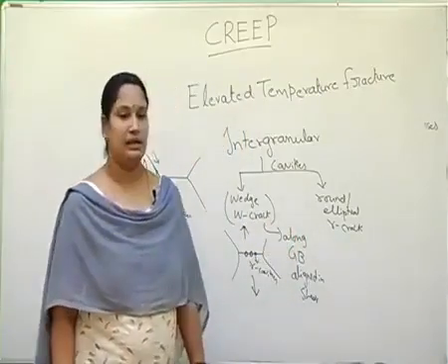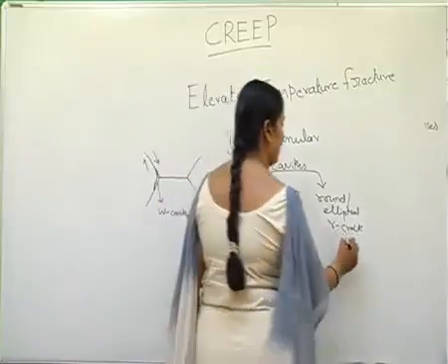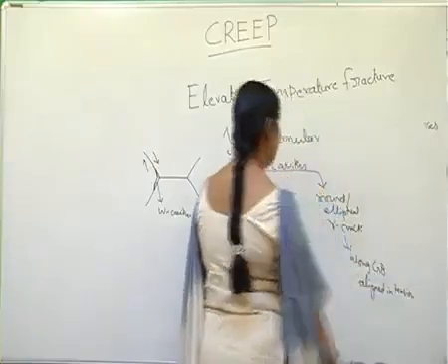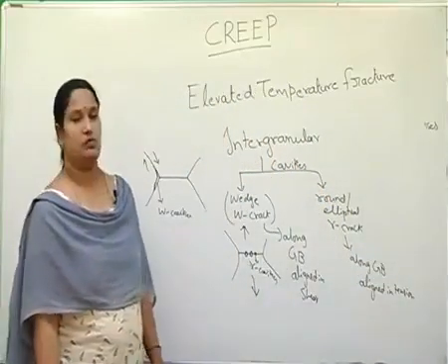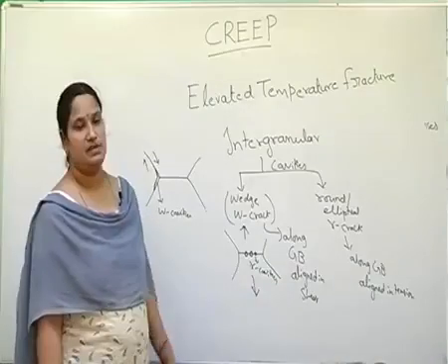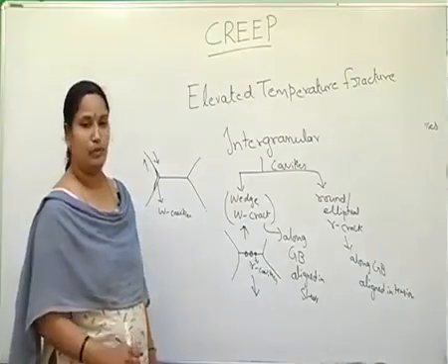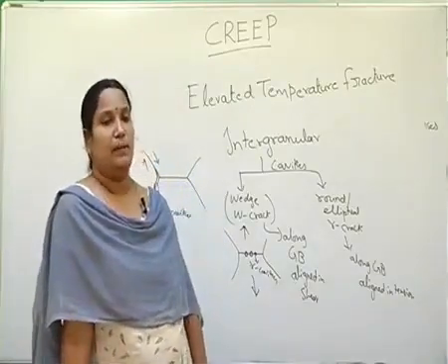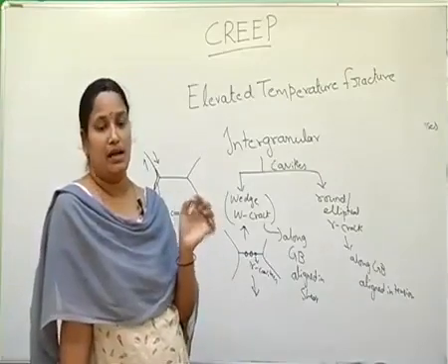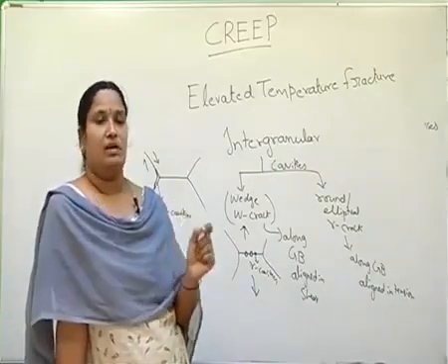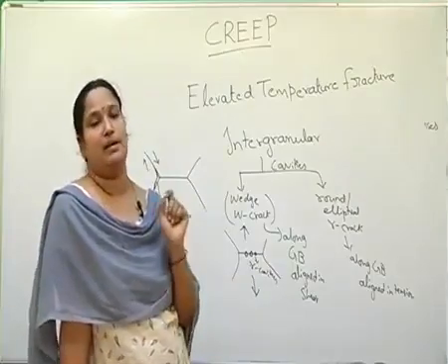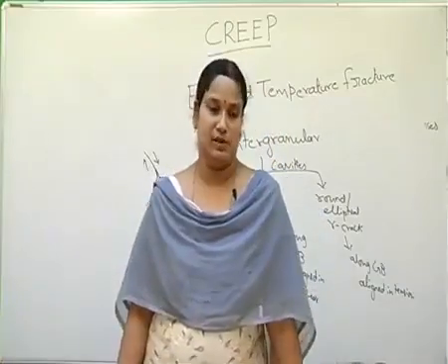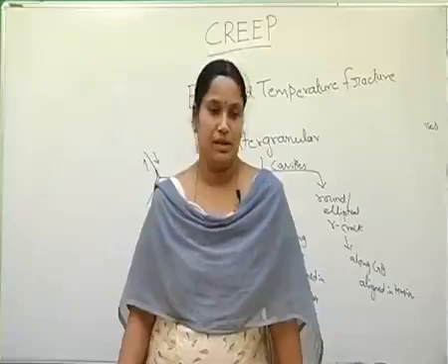And round elliptical or R-type cracks, which form along grain boundaries aligned in tension. So these are the two types of cavities which take place in the intergranular fracture mode. This intergranular fracture mode is promoted by the decohesion at the interface between the grain boundary precipitate and the matrix. Apart from this, other significant microstructural features also take place during stress rupture cracking.